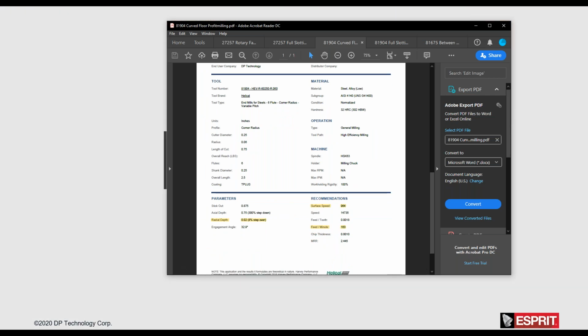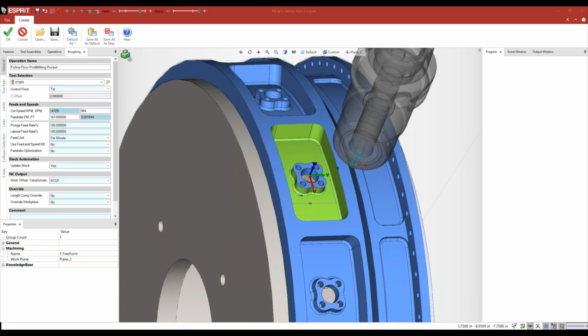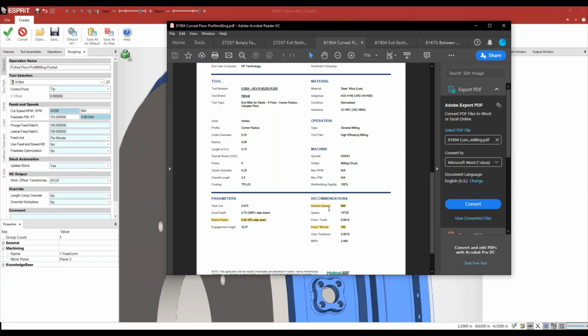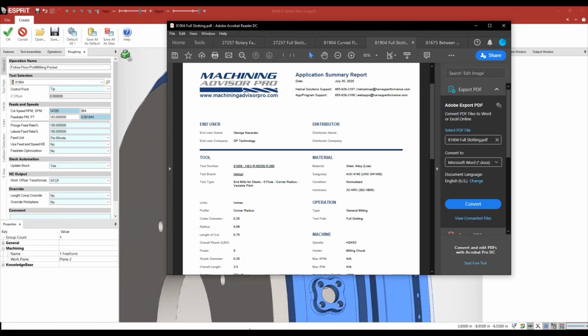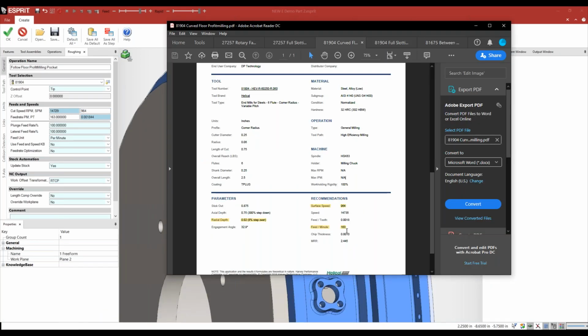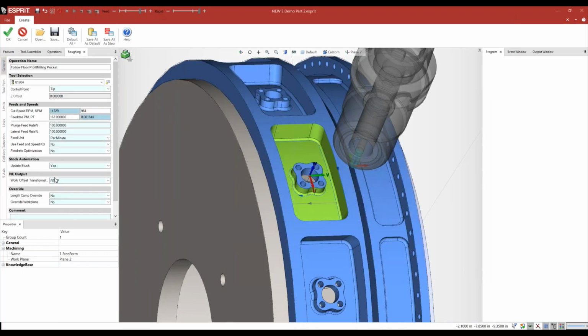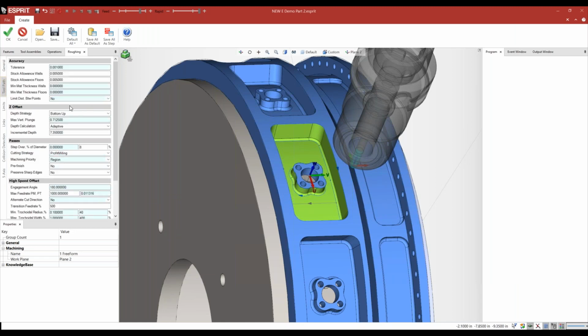Open up the tool and geometry. So my 964 is my surface feet per minute. Feet per minute 163, step over 8%. Another option in here, this is optional, but RTCP is available. 8% step over, so that's good.